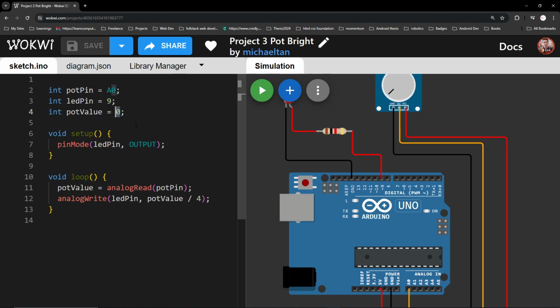If the Arduino receives the program and has power, it will start with a value of 0. For once, the Arduino will run this instruction, void setup: set the pinMode of ledPin, which is assigned to digital pin 9, as output. So the work of pin 9 will be output.